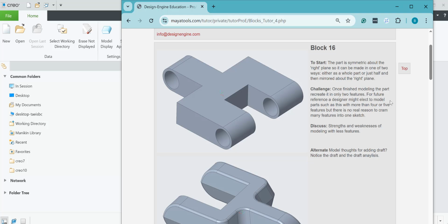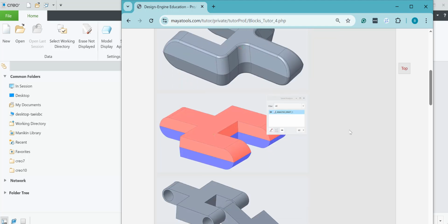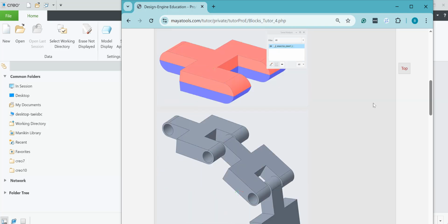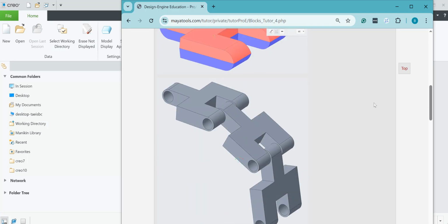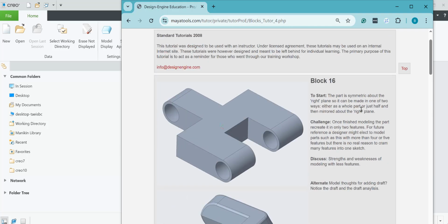I'm going to think about how I'm going to approach it from an R&D perspective, where you don't really care how it's manufactured. You're just going to 3D print it and let a manufacturing engineer worry about adding draft to the geometry. In this case, I have draft added to the geometry, and I'm using a draft check to see if everything's appropriate, and then I've added it to an assembly so I can move it around like a 3D printer chain might work. I'll make a handful of videos.